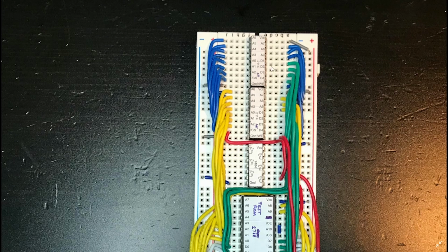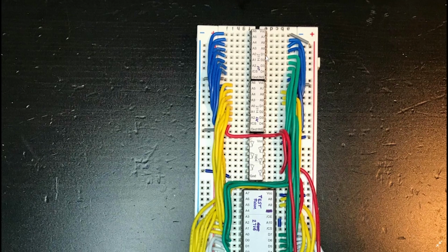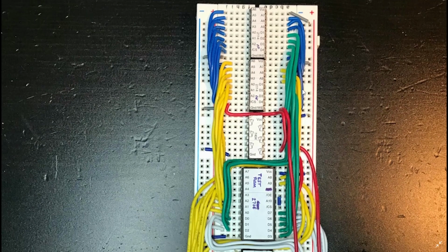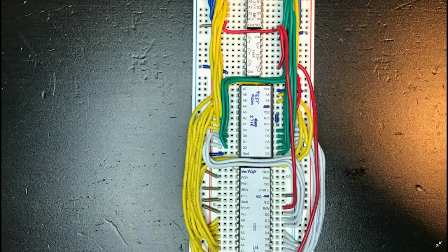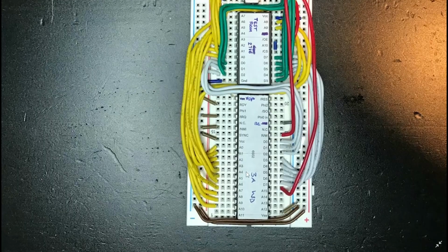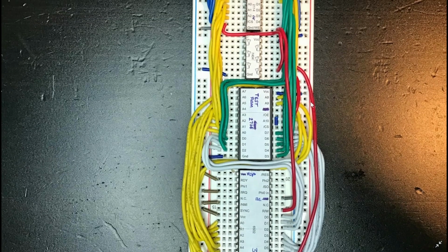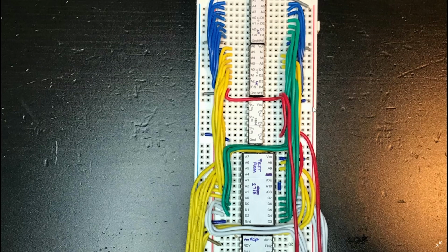It obviously can't access 8 bits there, so we want an 8-bit wide data bus, so we'll just use 2 of those, and so those would be effectively D1 up to D8. So you'd make sure that it corresponds to the same data bits as here in the ROM, and also on the data bus of the CPU, and you can just connect those together. No problem there at all.